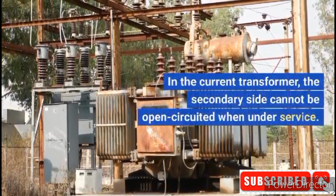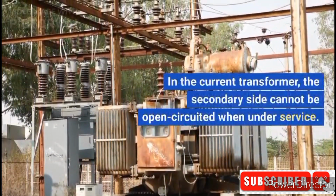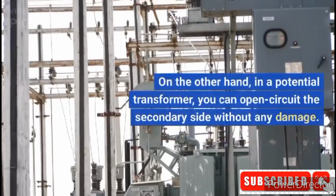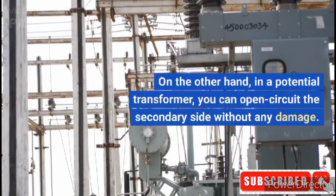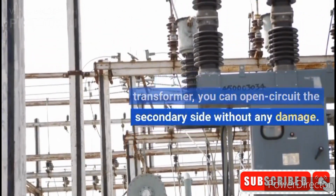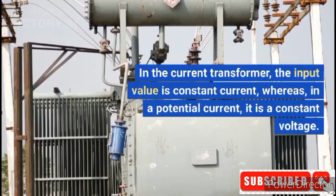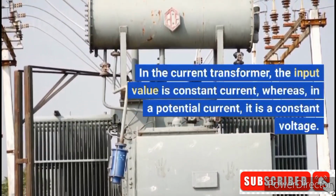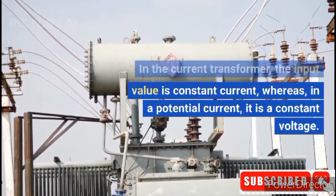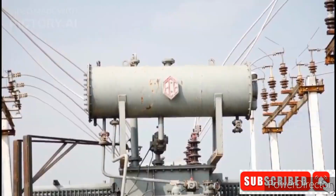Secondary side. In the current transformer, the secondary side cannot be open circuit when under service. On the other hand, in a potential transformer, you can open circuit the secondary side without any damage. Input value. In the current transformer, the input value is constant current, whereas in a potential transformer, it is a constant voltage.